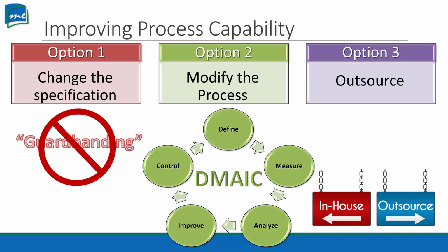If the engineers are saying, okay, 1/2 inch or even 1 inch is acceptable as a plus or minus, they might say, okay, well, 1/2 inch is acceptable, even though it can go up to 1 inch. So they'll make it even tighter because they're expecting poor quality. So they do what's called guard banding.